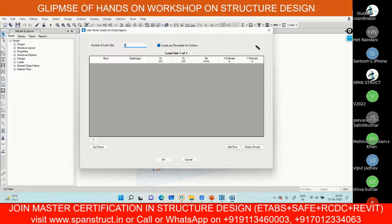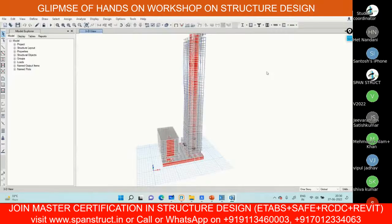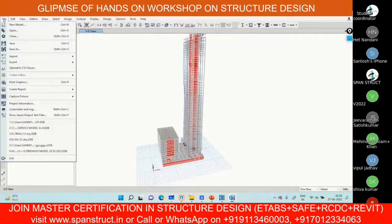You don't need to give all the Fx values and all. It will automatically calculate the Fx values and it will get applied to that building. But in the case of the gust factor and all, you have to give the user load, and through the user load, you have to give all this data here, Fx value, Fy value, and Mz value, and you have to apply. This will come story wise. And this will only appear when you apply the diaphragm. So when the diaphragm is not applied, in that case, it will not work. So you have to apply the diaphragm. In that case only, the wind load will get applied.